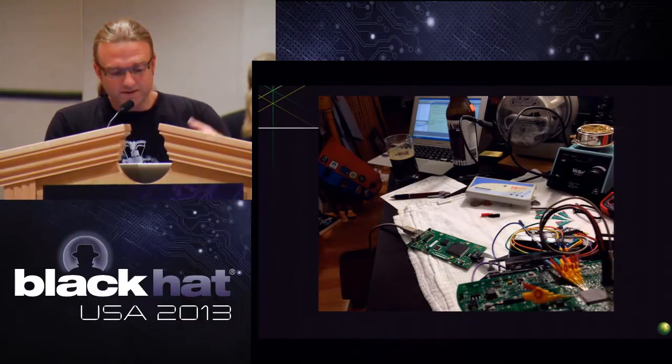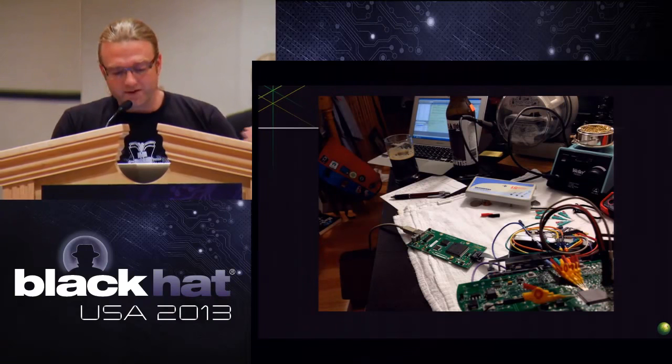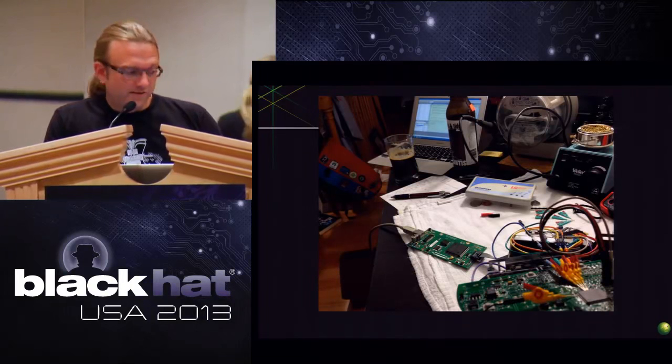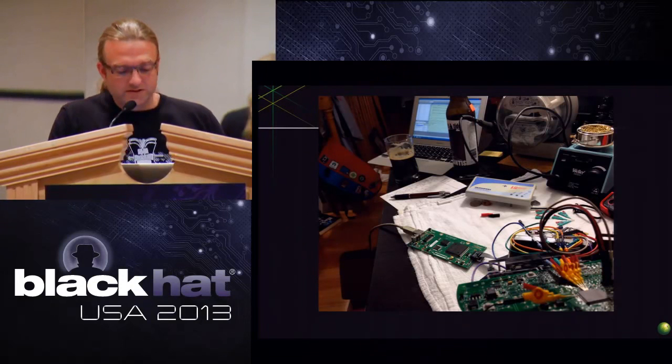But you can see like halfway back, we've actually got the vendor supplied debug port. So I'm able to control debug at a software layer, and as I'm doing that, those little micro grippers are letting us do a full logic analysis on what's going on the wires, so we're able to track more things than the vendors let us get to, and start digging a little deeper.